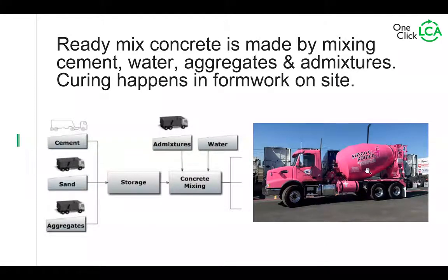So much for cement. So when we have this cement, we take a bag of that, we take a lot of sand or aggregates, and we mix it with admixtures and water, and we put it in a nice truck, and the truck will rotate so as to not let the ready-mix concrete start to cure, and then we pour it or we pump it in a formwork.